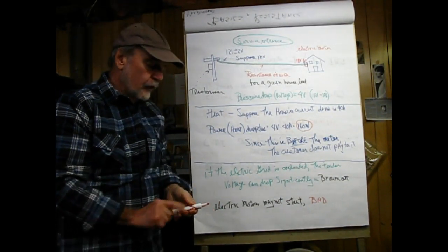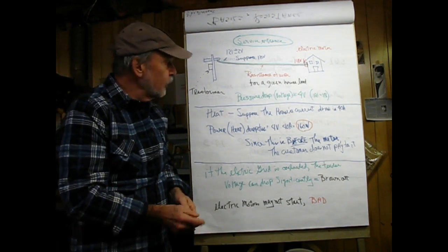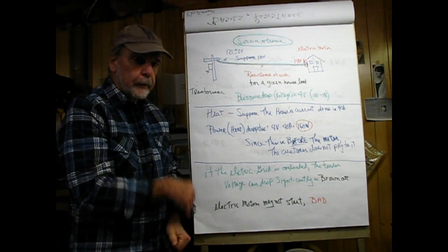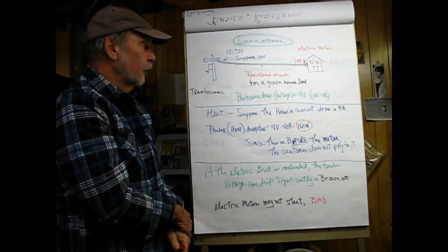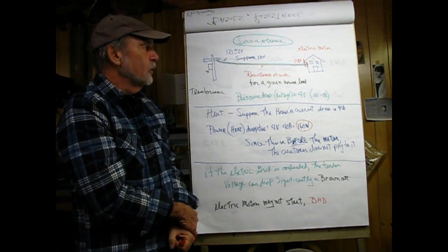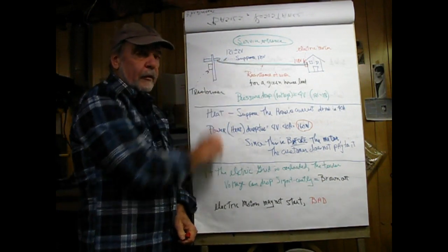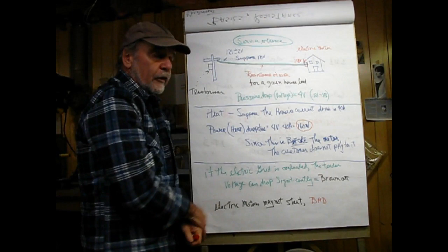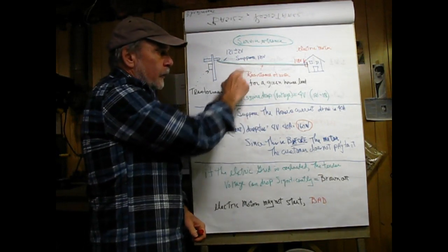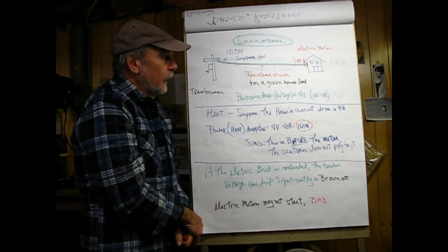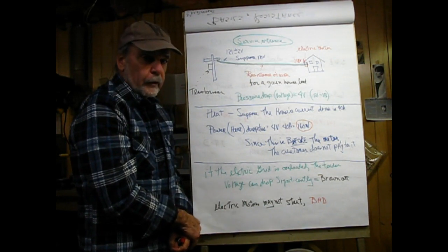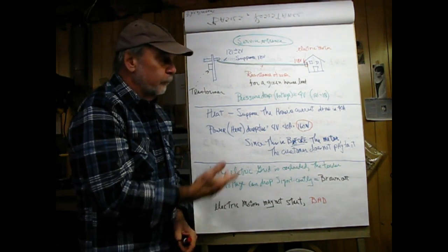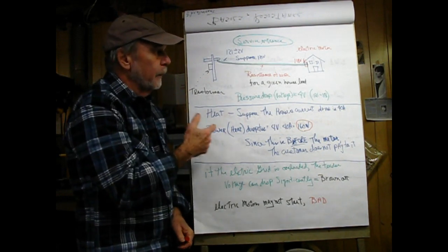So take another example. This would be the service entrance on a house, and sitting at the pole here we have a transformer, and this is alternating current, but right now it doesn't matter, same principles apply. And the feeder voltage should be 121 plus or minus 2 volts. Now, I'm only showing 2 leads coming in here. The black lead is actually the support lead. Usually there are 3 leads, including the support, for 240 volts, but in this case I'm not being concerned with that.